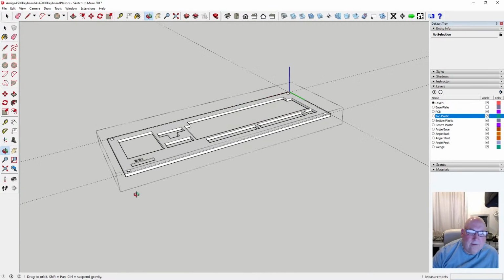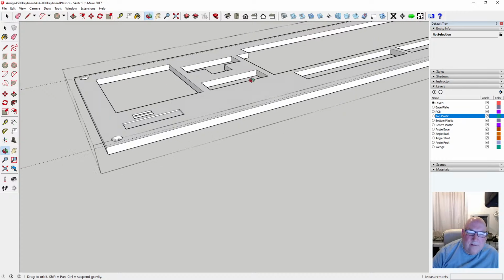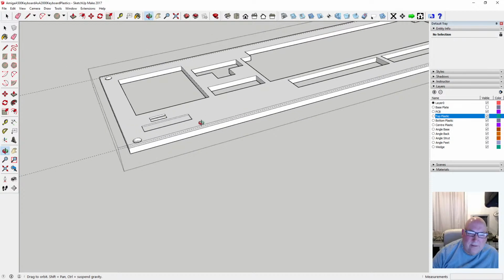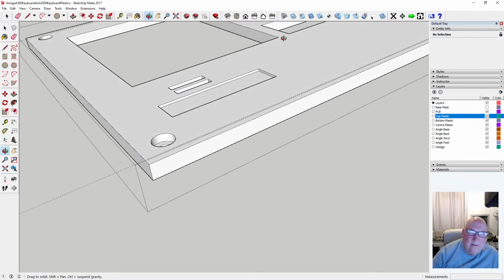Right, so there's the last few here. Now, we're going to have a look at these corners. Yeah, I might have to put some of them corners in, because sometimes when it mills it does a quick sweep and then you get one corner that's different to the other. So if we purposely make the corner, we're going to have a look at that in a minute.